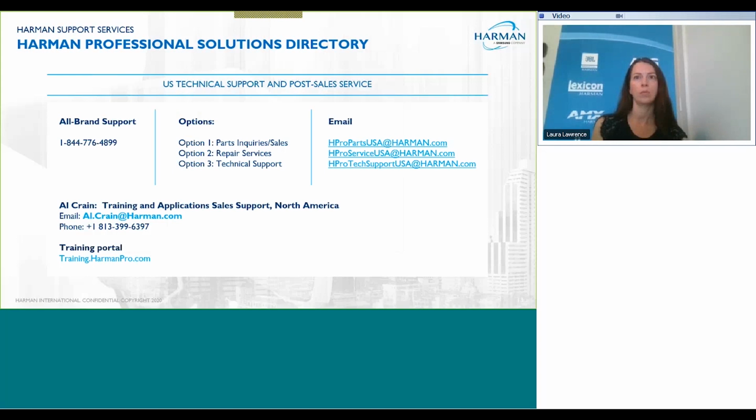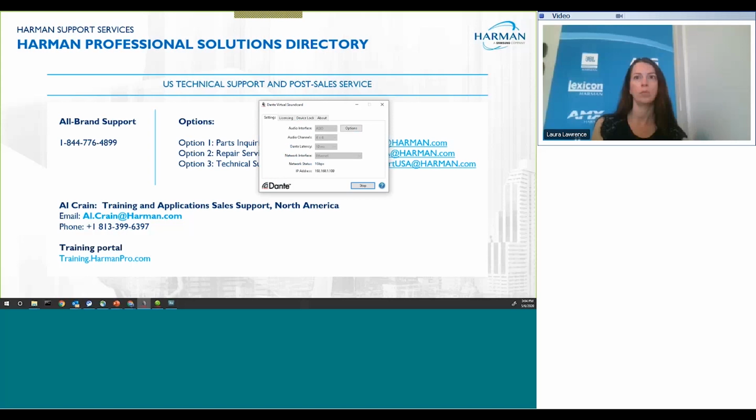That gets converted to Dante, and then I send Dante across my house network into my laptop, and then I receive that audio using the Dante virtual sound card. And I can pull that up, actually. I actually have it running right now. So this is the DVS, and if I stop the DVS, I can change the channel count to anything up to 64 by 64. That's how you bring audio in via Dante.